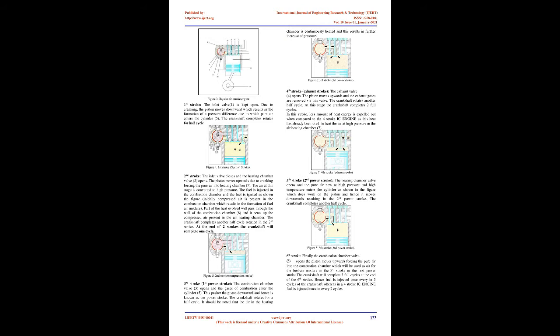The top and bottom crankshaft are connected via a drive chain or toothed belt. The top crankshaft and piston become positive power contributors to the overall power output, thus increasing the amount of power and torque generated by up to a possible 35%. In essence, the engine results in having 2 pistons operating and producing power within each cylinder. The absence of valves, springs, retainers, and guides means that the engine's bottom end has been freed up from laboring and is allowed to spin up, producing more power.